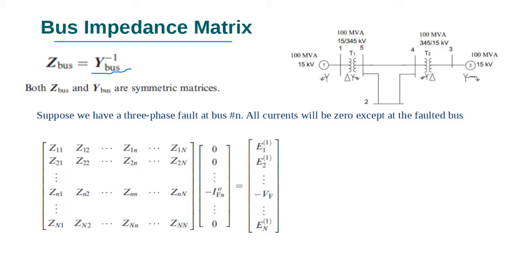We discussed in load flow the Y bus, which is the nodal analysis. And I asked you the nodal analysis, how to find the Y bus. If we invert the Y bus, this is straightforward. If you remember that we convert the impedance into admittance.